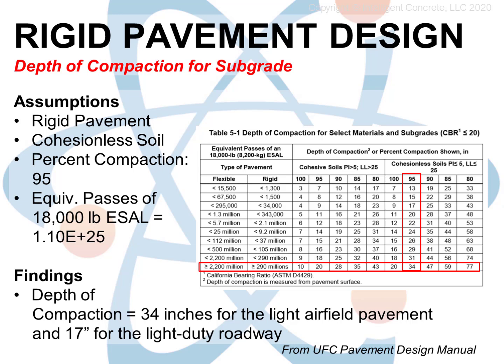If you remember from our first example with 28,000 passes of the controlling vehicle, and then look at the chart, we'd only need 17 inches of compacted soil below the concrete surface. Just note that these depths of compaction have not been rigorously determined for our site-specific soil or the conditions that we have. They are tabular values aggregated from a huge number of construction projects peppered with failures.